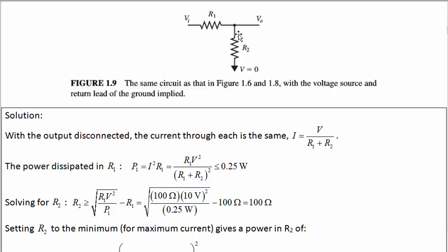What happens when you exceed the power limit of a resistor? It depends on what kind of a resistor it is. Certain resistors will fail to open, certain resistors will fail to closed, and there's some randomness involved too. What do these terms mean? Failing to open means that when the resistor burns out, it's not a conduction path anymore.